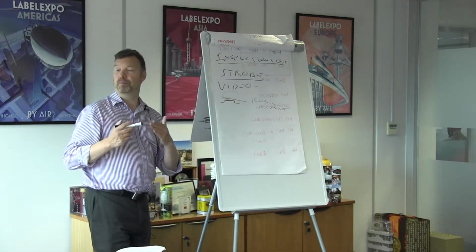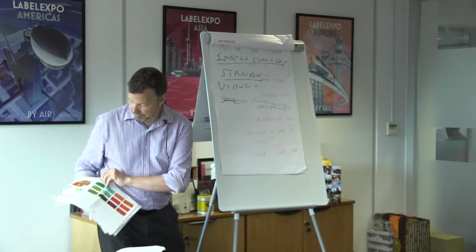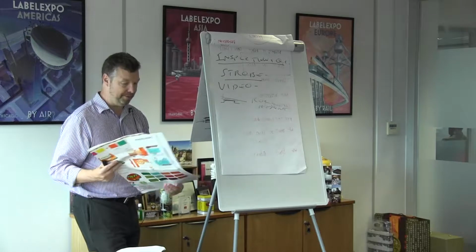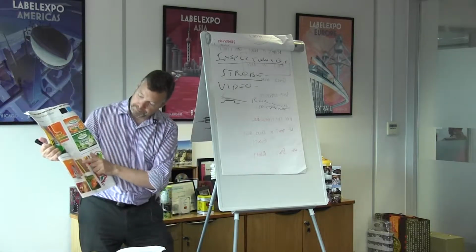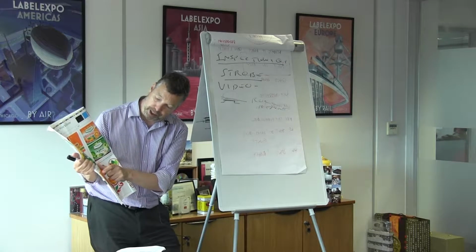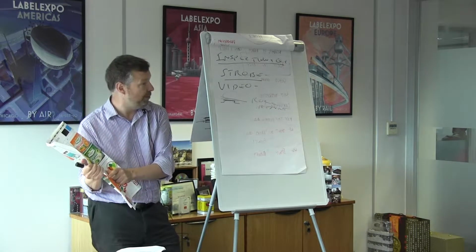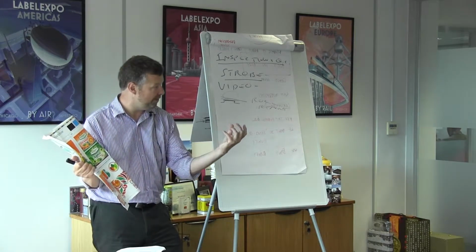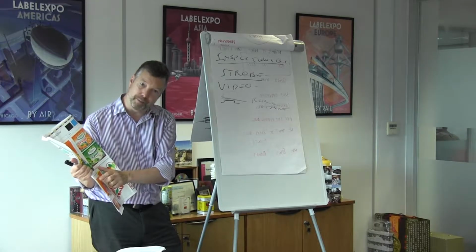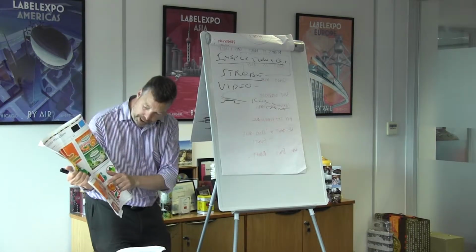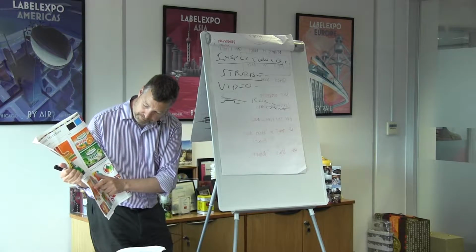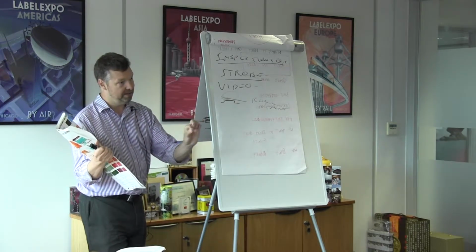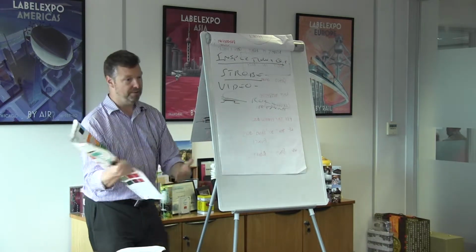So, for example, some defects are going to be terminal for a job, and some aren't. That's a matter of human judgment. If you had this image here, and let's say you had a slight bit of pinholing up here, but actually you've got an area there where you're probably not going to notice it because it's a kind of dappled type of area. So getting the little pinholes there might not be an issue to stop the job. If you start to get pinholes there, or in sunglasses, then that's a massive problem because you're going to see it instantly. You can see there's a hole in the image there. So there's the kind of human judgments.